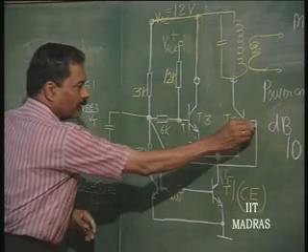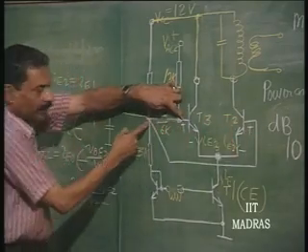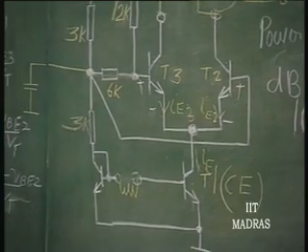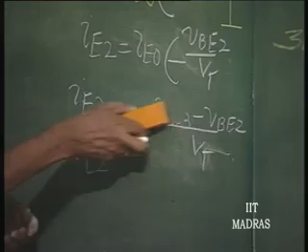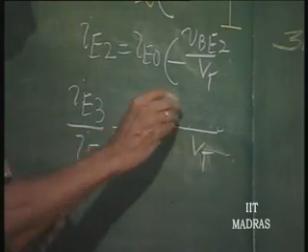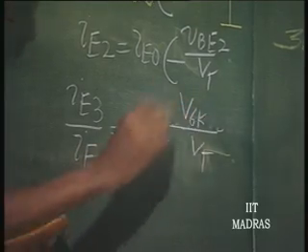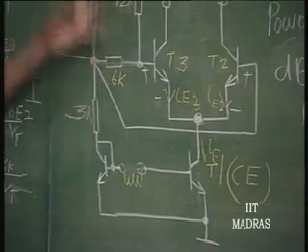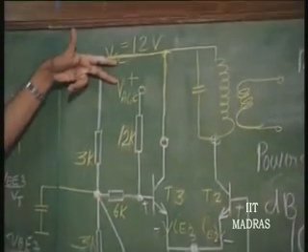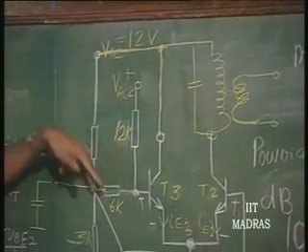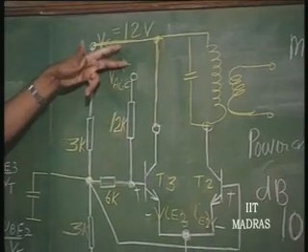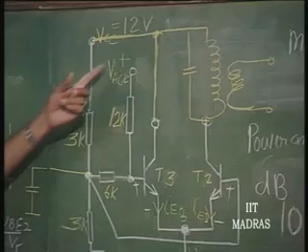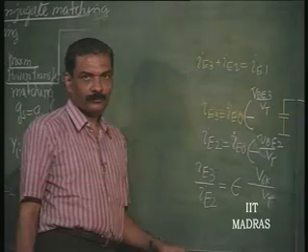This voltage minus this voltage is the voltage across 6K. And voltage across 6K is governed by voltage VAGC with an attenuation factor. So, voltage across 6K is governed by how VAGC is varied.